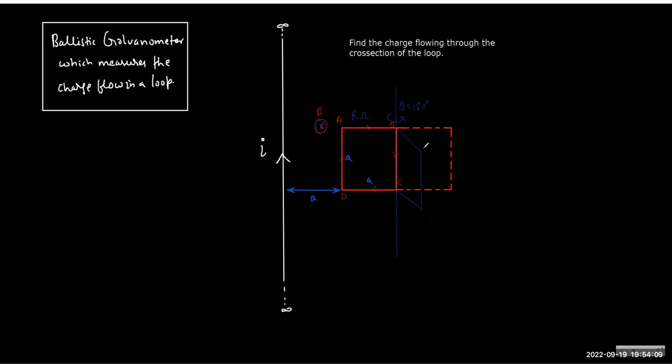In the next part, when you are here, so let's say A has come here and B is there, C is there, D is there. In the next part, when you go from here to here, the flux will further grow, right? And because the flux is in the growing phase, how will the current be? Because the inward flux will grow, it will try to create the outward flux.